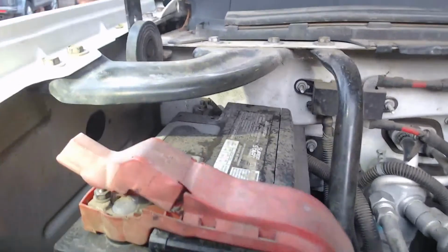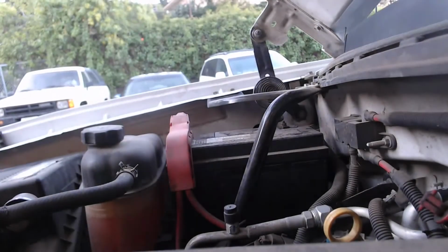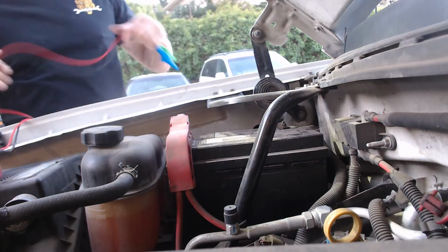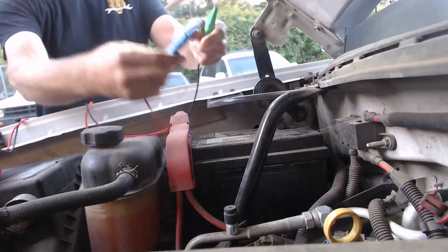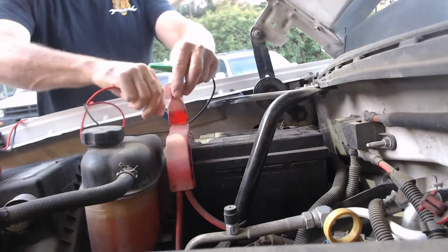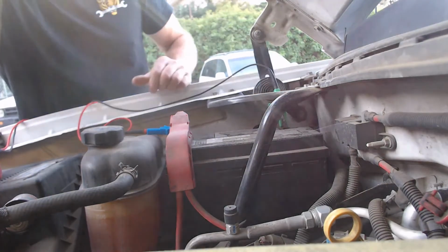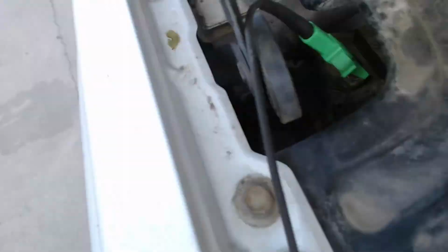I don't see a date code handy to know how old it is, but what we are going to do, and actually maybe I could put this up here and look across it like that. I'm going to take the voltmeter, and the first thing we're going to do is what we call charging system voltage. So we're going to look at the charging system voltage on this guy, and I know you're just fascinated by my professional recording skills. So I'm going red to positive, black to negative across the battery. So there's my leads. I just use the alligator clips to get onto the negative there, sorry, the positive there, and to the negative there.